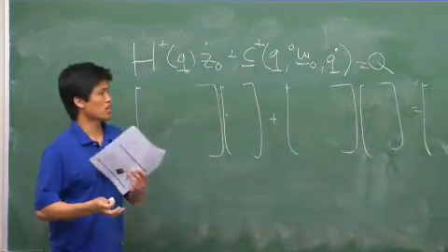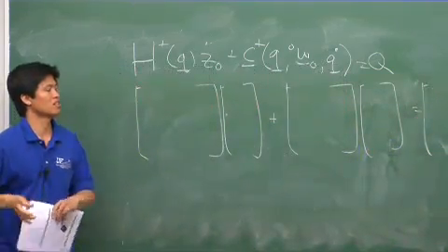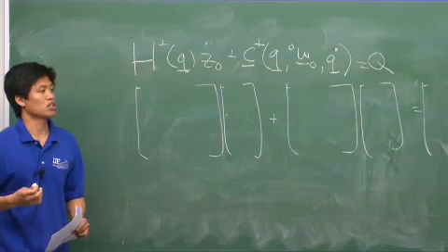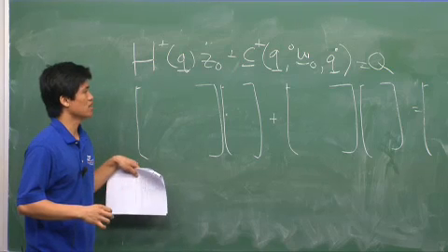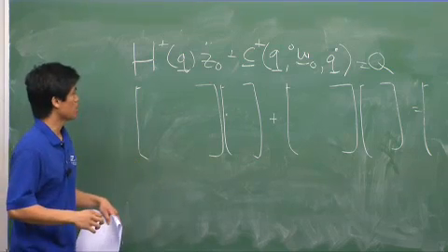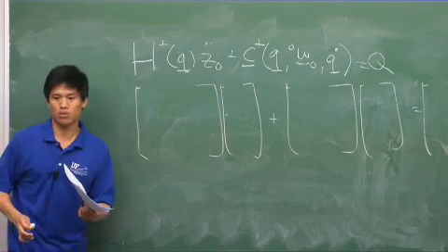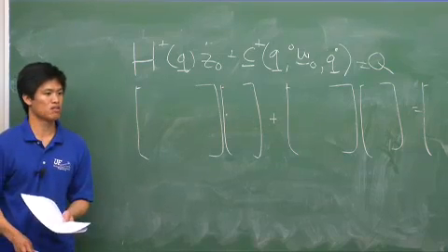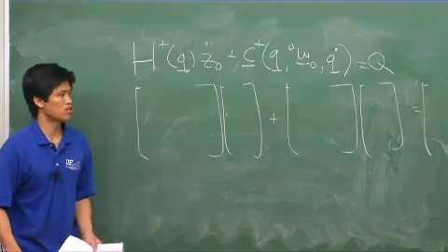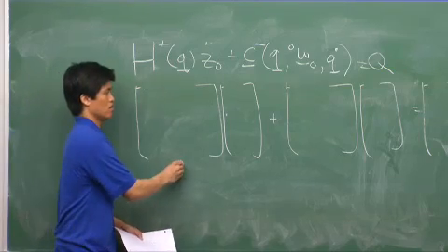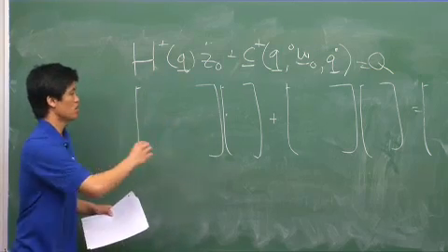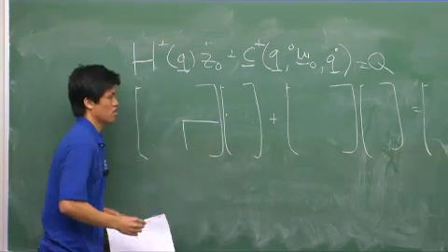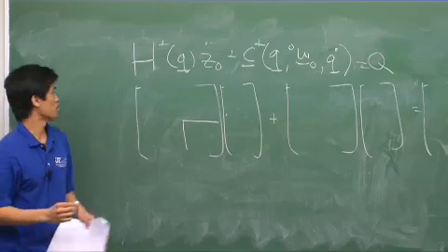So what I mean by decomposing the dynamics of the entire system and holding certain variables constrained is that we can look at what exactly is in these matrices. We know what the equations of motion are for a fixed-base robot arm manipulator. In the way we write our equations of motion, this encompasses our whole system, but we can look at a subpartition of the bigger matrix.